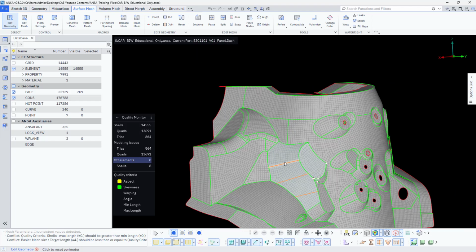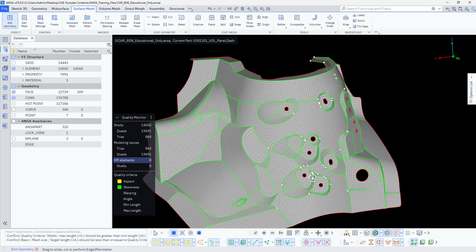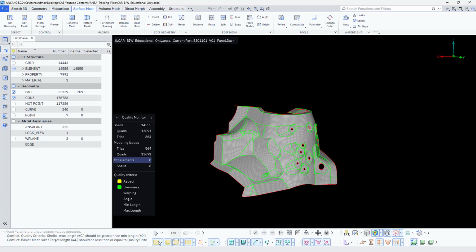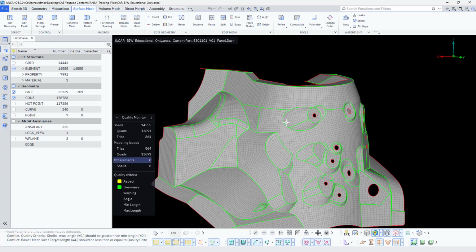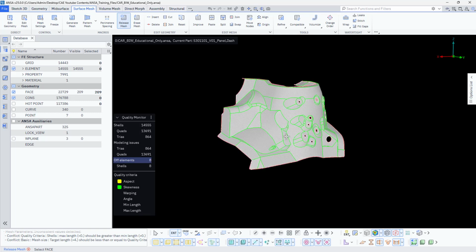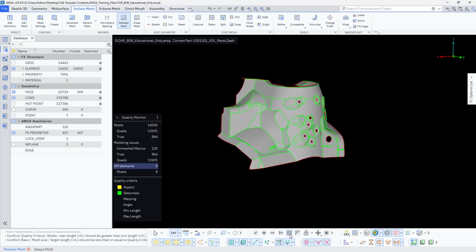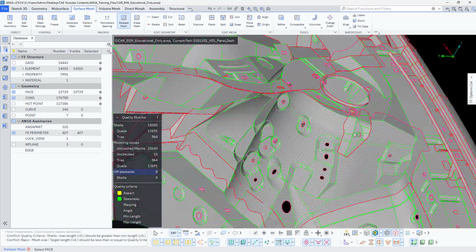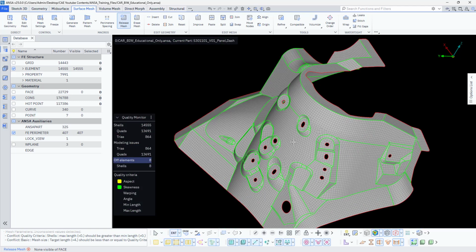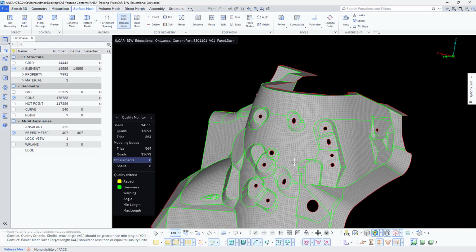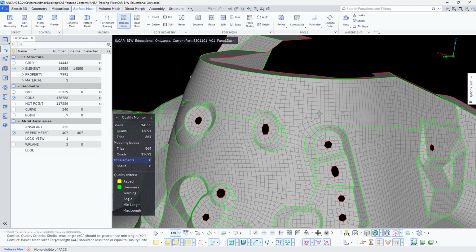Okay, so once you fix everything, you can release the CAD. So we have the CAD as well into account. Okay, it is attached to CAD now. So what you can do is you can directly go to release mesh, select everything and middle click. Now we have the whole CAD in the model. Okay, and this is the meshed model. If you just uncheck this CAD, you will have only the meshed model. Okay, so this you have it now. So I hope you already got to know how to deal with this.